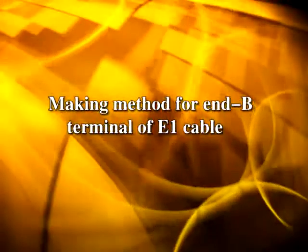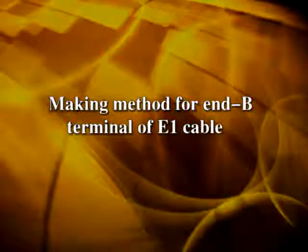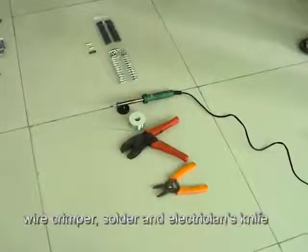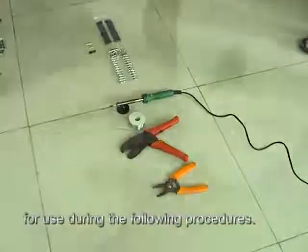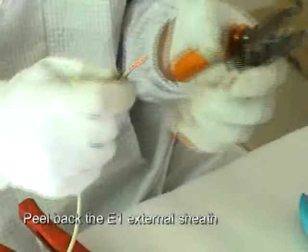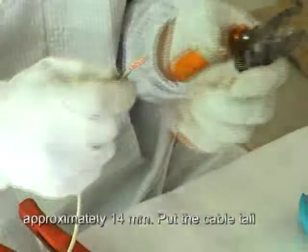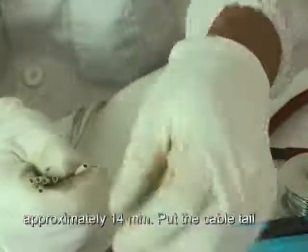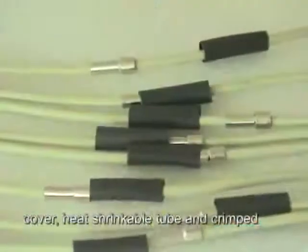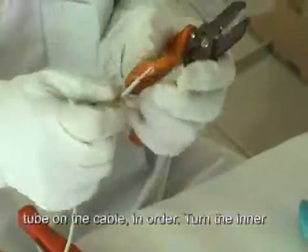Making method for NB terminal of E1 cable. Prepare tape measure, electric soldering iron, wire crimper, solder and electrician's knife for the use during the following procedures. Peel back the E1 external sheath approximately 14 mm. Put the cable tail cover, heat shrinkable tube and crimped tube on the cable in order.